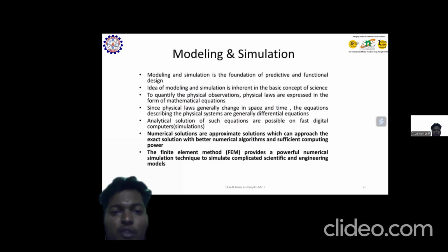To interpret the results, we have to analyze all the steps: first, discretization of the solution domain and material assignment, then the stiffness matrix of the individual elements, force vectors of each node, and displacements.